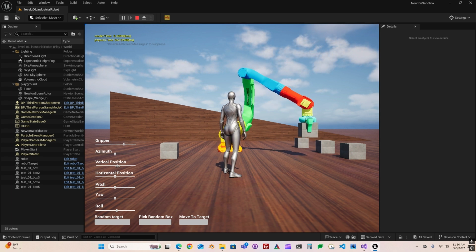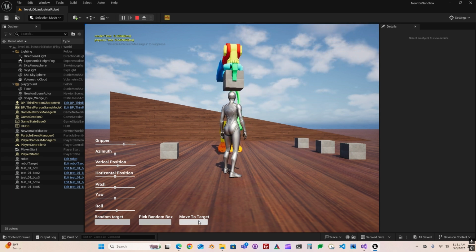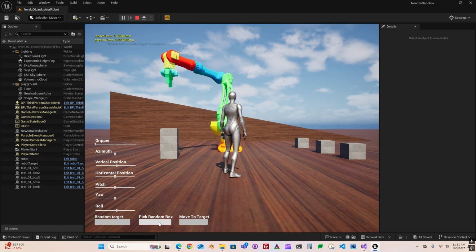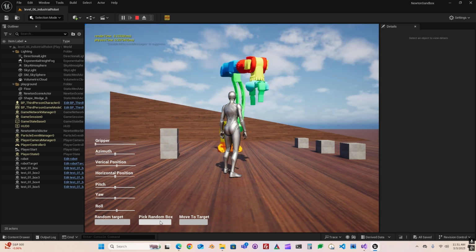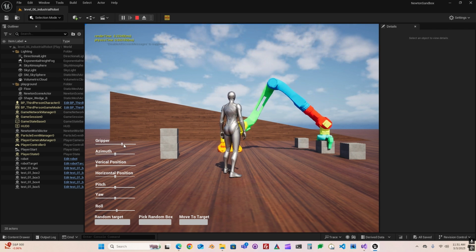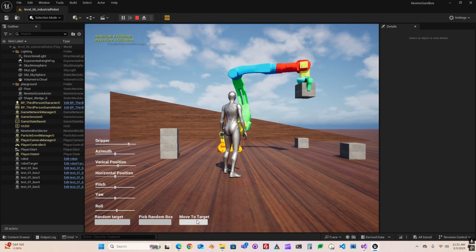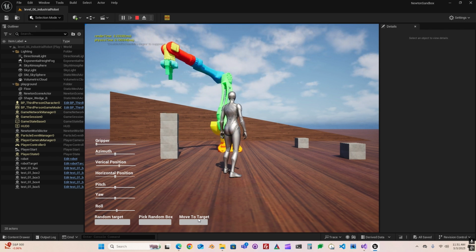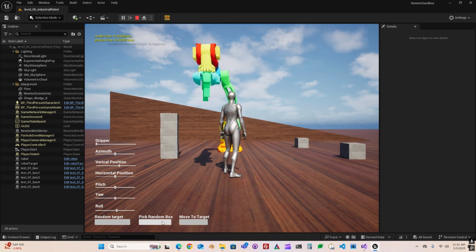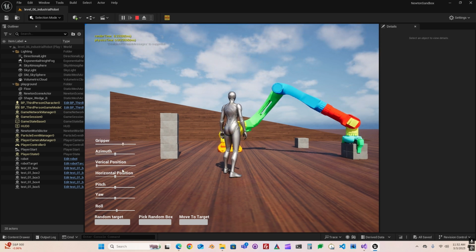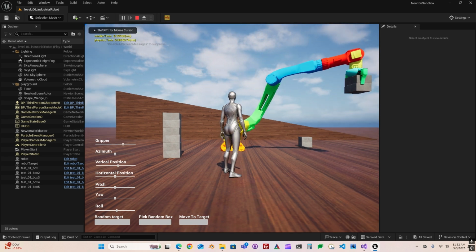While inverse dynamics is a powerful approach, it has some limitations. Gimbal lock. The algorithm assumes that all degrees of freedom are independent. However, in certain cases, 1 or more degrees of freedom may become a scaled value of another, leading to a loss of control. This issue is known as gimbal lock, and it is undesirable. Reachability constraints. Not all targets are physically reachable. The set of all reachable targets is known as the robot's workspace.